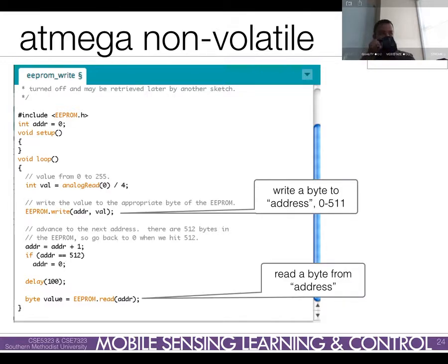Okay. The one thing you'll want to do here is, again, there's nothing protecting this memory, right? So if you want to write something to an address on the EEPROM, you want to keep writing across the entire EEPROM so that you increase the life cycle of that EEPROM. So you don't always want to write to the first address. You just want to go into it and write at different places. Is that fair? Yeah. Okay.